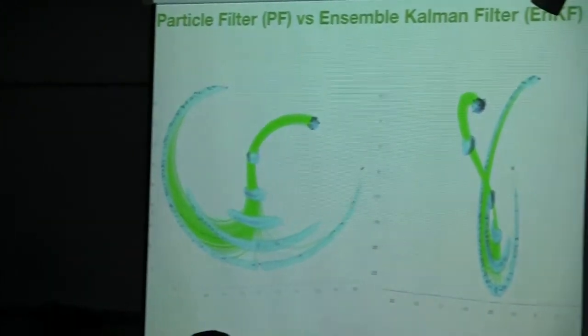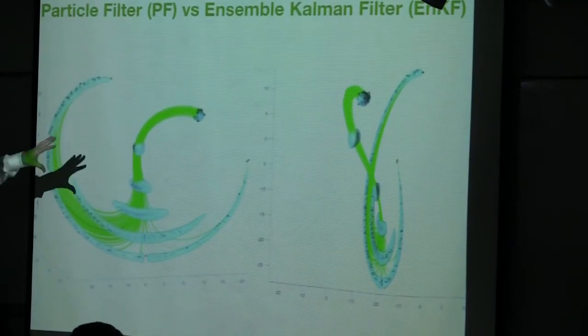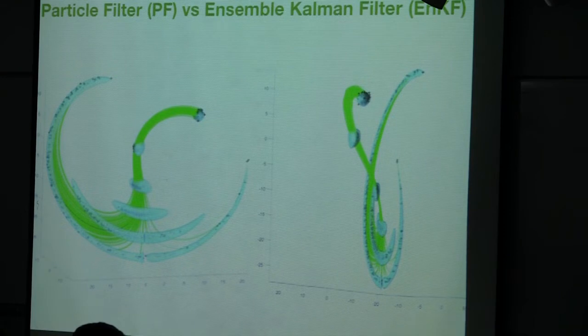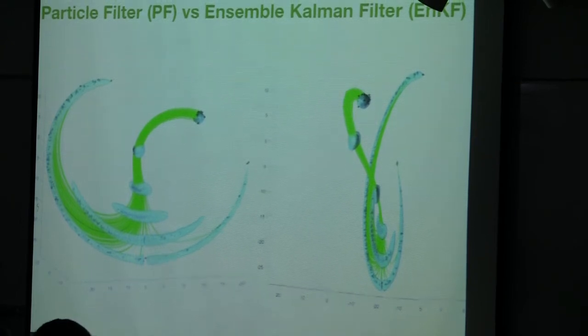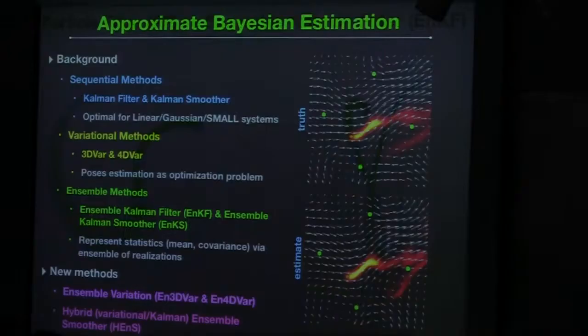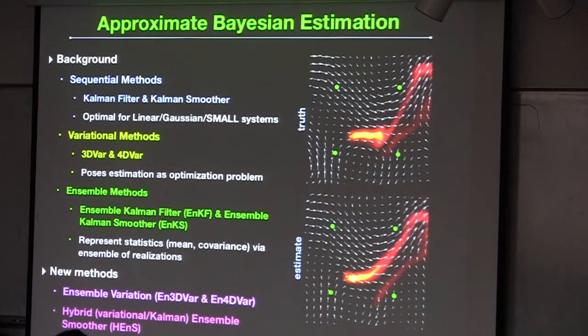And that is, in 10 minutes, the explanation of, in my experience, why the ensemble Kalman filter method scales with dimension so much better than the particle filter method. Particle filter method, there are still a lot of people using, and I would like to engage with people in this comparison of the scaling of the two problems with dimension, because I think we're naturally, as controls folks, interested in problems with dimension higher than 1, 2, or 3. And in those cases, in my experience, the ensemble Kalman filter every time wins out. Maybe we can follow up on the discussion afterwards.